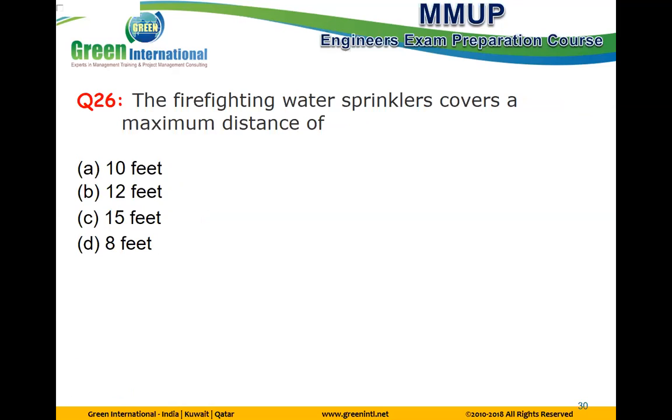A firefighting water sprinkler covers a maximum distance of 15 feet. C. Does anyone have another answer? No. Actually 15 feet, which refers to 4.6 meters in light hazard.